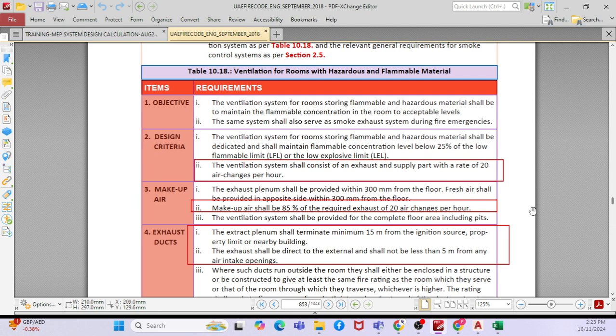There are many cars which consist of fuel as well. But that particular one we will not handle that way, since it is a large car park area, you cannot go with a clean agent system or a foam system. Actually it is a class B fire only, but when we consider it a one-time fire, we normally apply a sprinkler system as per the local code.